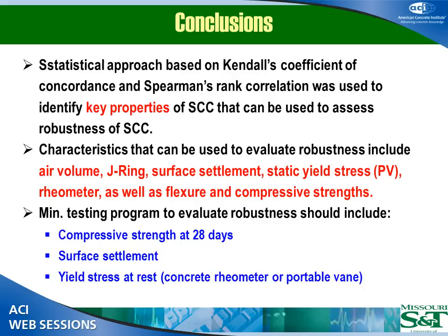Okay, the question is why do we choose plus and minus 1% on changes of humidity of the sand versus 10% on the super? These are within, if you look at many recommendations, you can even look at some of the reports from NCHRP, etc. But these are within production variations. For example, if you're using 900 kilograms per cubic meter of sand and you're changing that plus or minus 1% humidity, that means it's plus or minus 9 liters of overestimation or underestimation of water.